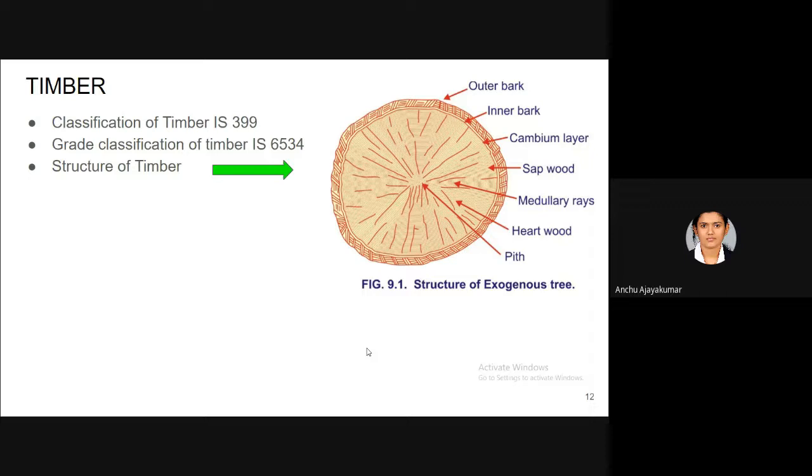Next is the sapwood. After the cambium, moving inward, next is the sapwood portion. It assists in the life process of the tree by storing up starch and conducting sap. The cells in the sapwood are active. Next portion is the heartwood. Heartwood gives strong and firm support to the tree. With the growth of the tree, the cells in the inner older portion of the trunk gradually become inactive and lifeless, but do not decay.